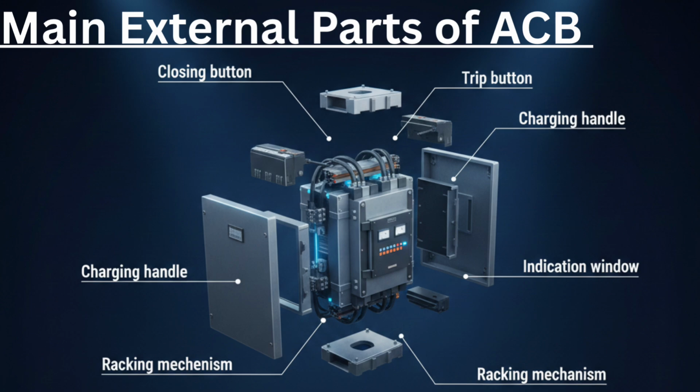These external parts allow operator interaction. Always check the indication window before operation. Never assume breaker position. Draw-out ACBs allow safe maintenance because they can be removed from the bus bar without disconnecting cables. Understanding external parts is the first step before going deeper inside.